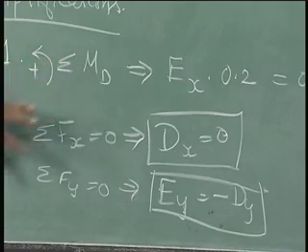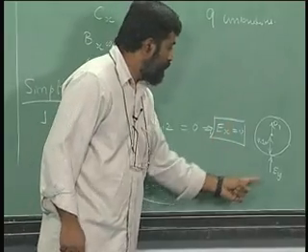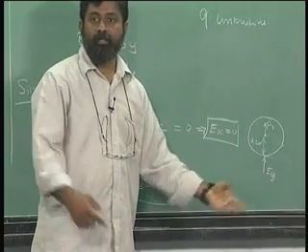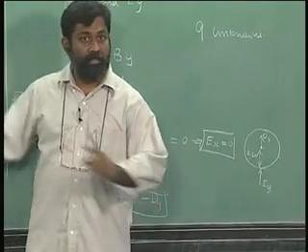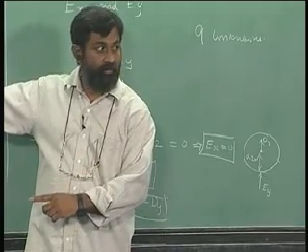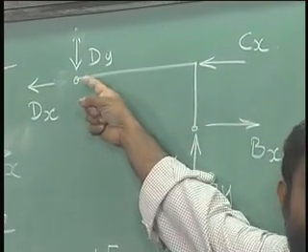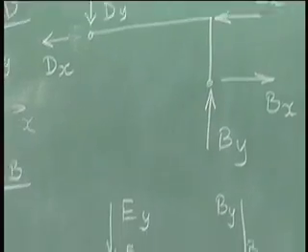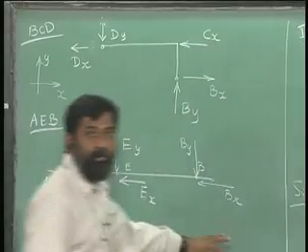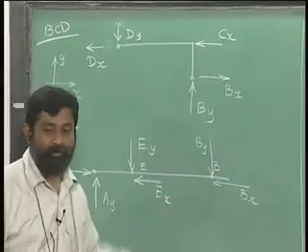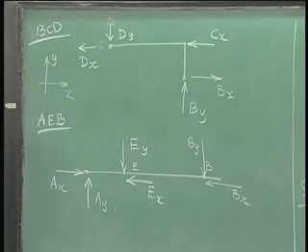I need not now look at all these 4, I just need one unknown, either Ey or dy, and that will reduce the unknowns in the other free body diagrams. You have dx and dy here, you have Ex and Ey over here, alright. So, let us seek to now remove those so that we simplify. Okay. Please remember, these simplifications will help us solve in a much better way.